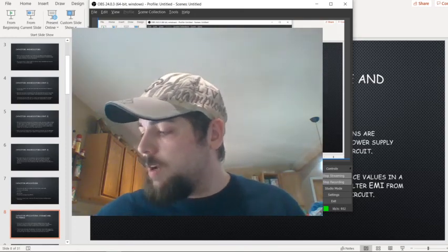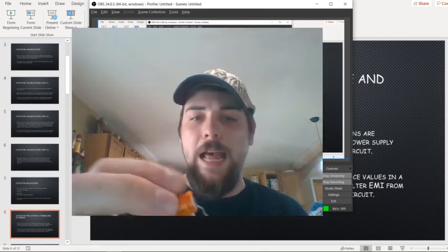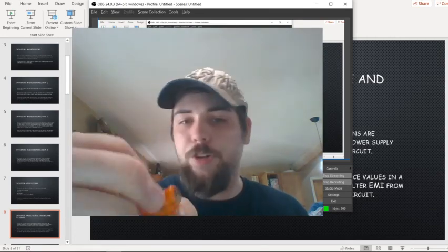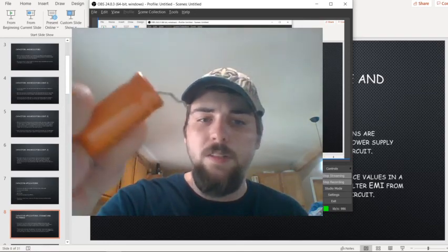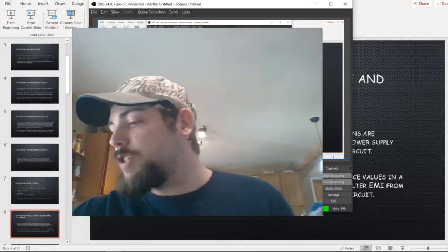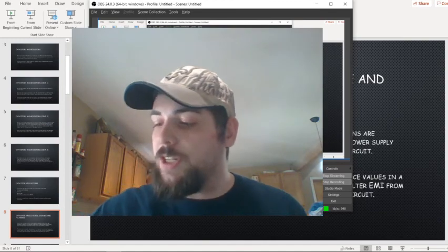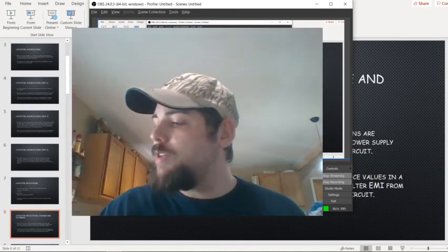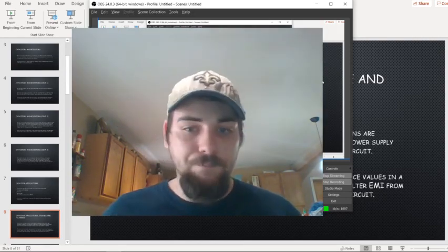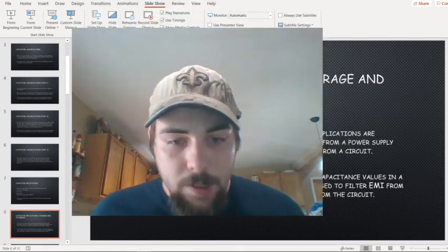But yeah. Oh, and I should also mention that in these axially leaded capacitors, generally they put the positive side on the little lip. But that's just in certain cases. It's not a rule, but in these ones it is. So be careful about that. All right.